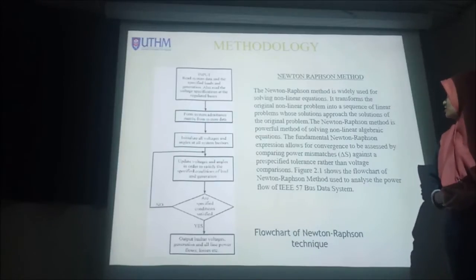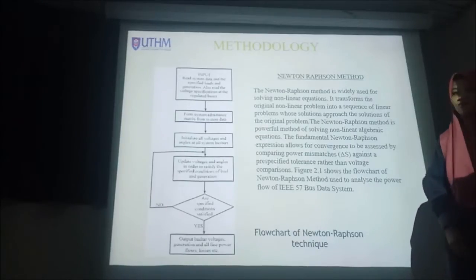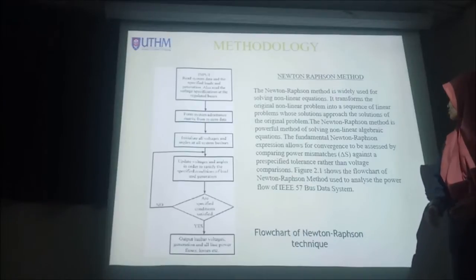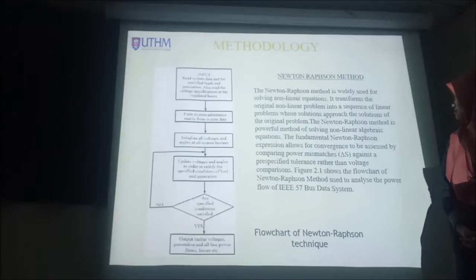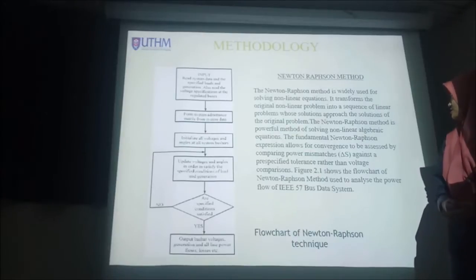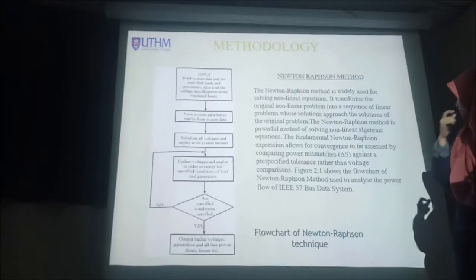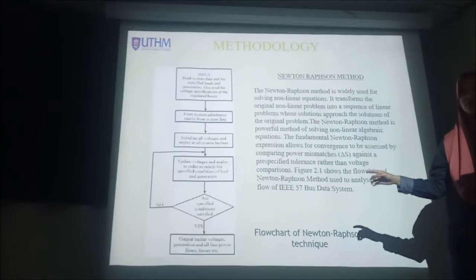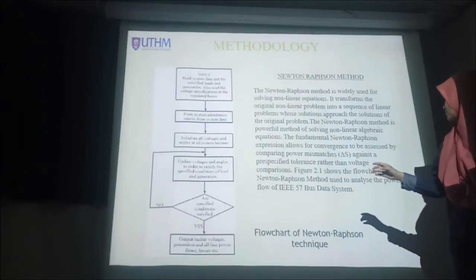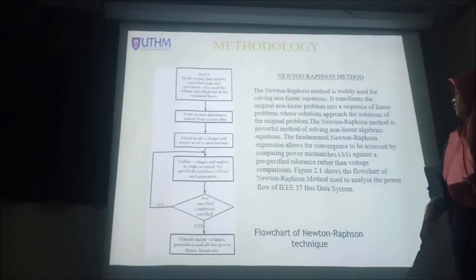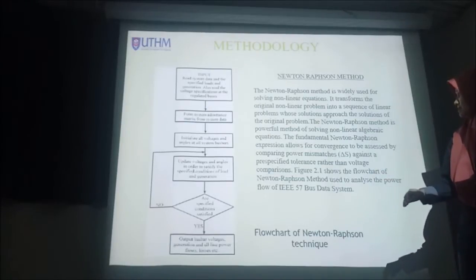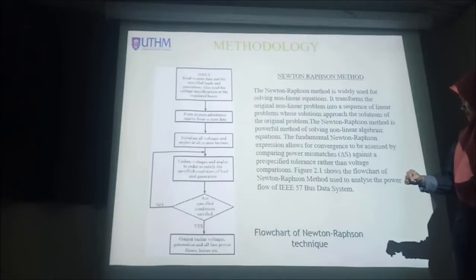The fundamental Newton-Raphson expression allows convergence to be assessed by comparing power mismatch against a pre-specified tolerance rather than voltage comparison. Figure 2.1 shows the flowchart of the Newton-Raphson method used to analyze the power flow of the IEEE 57 bus data analysis system.